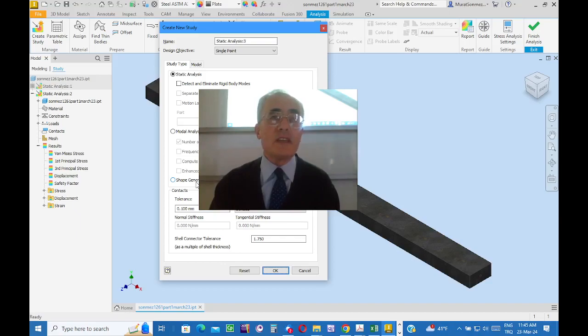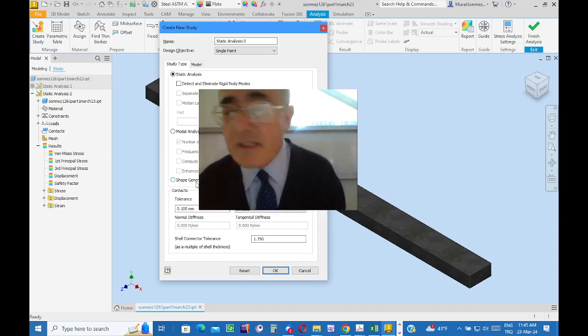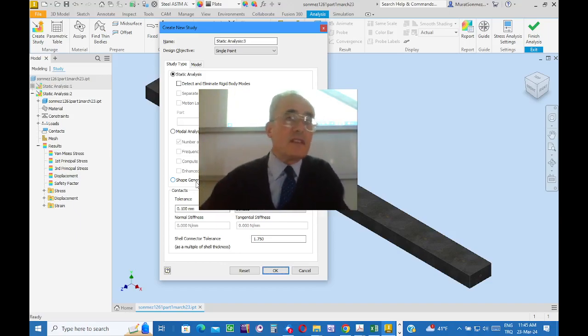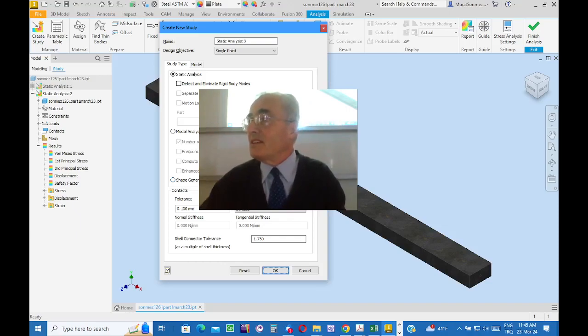If the factor of safety is much greater than 1, 2, 3, 4, for instance 15, 20, etc., then it indicates that over there you can decrease the material. Either decrease the size or completely have an empty space. So, well, here, if it is the case, then select the shape generator option, you know. But in this short course, there will be no example, no demo of how it is done.